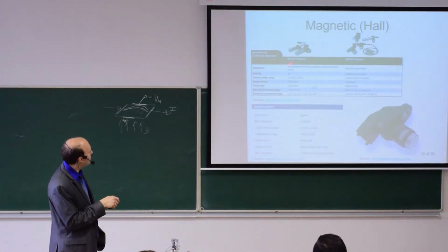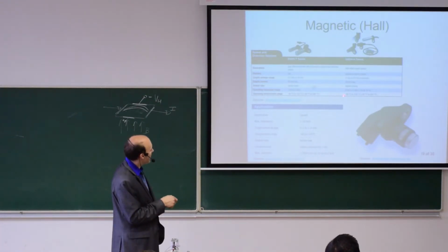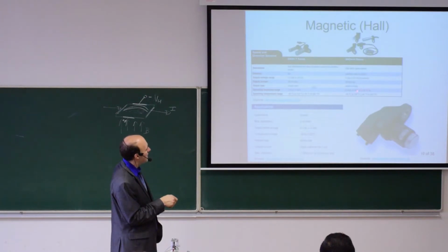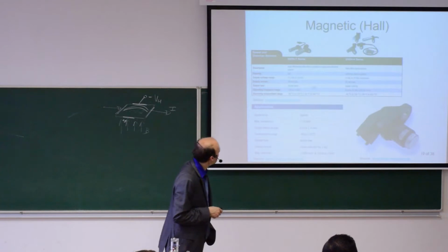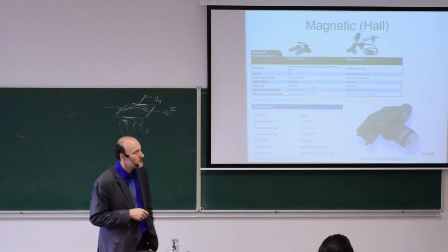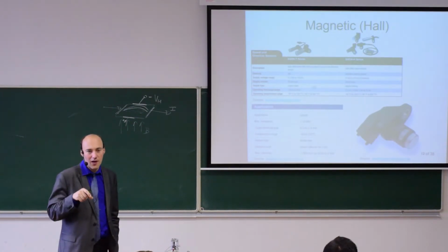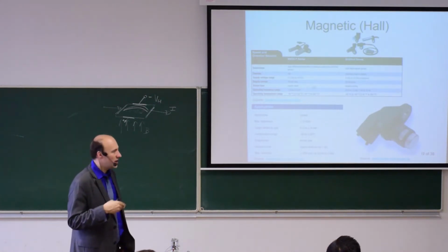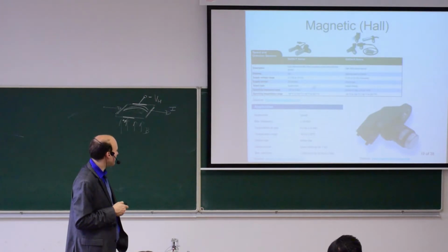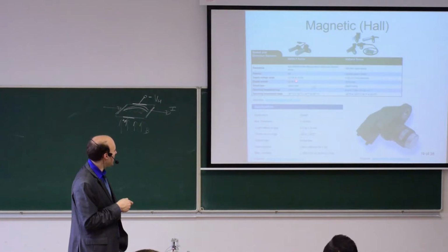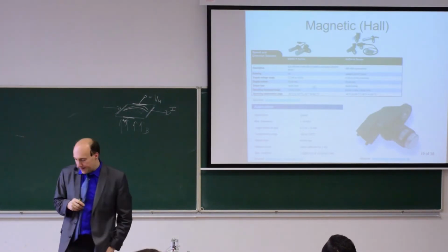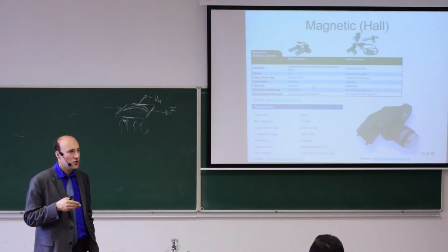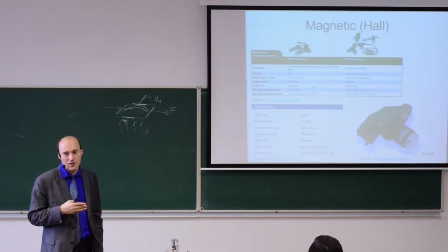What you see here again are two examples of automotive sensors. They say from 0 hertz to 15 kilohertz in one version. In another version there is a high pass filter, so from 2 hertz to 15 kilohertz, no, 15 hertz in this case. I think there is a K missing. And in this one you see they limit it above 1 hertz up to 15 kilohertz. So not all sensors based on this are able to work from 0 speed, but still 1 hertz frequency is quite low. You can see the power supply voltage range here from 4.5 volts to 18, which is well within the normal voltage that we have in industrial applications, which is 12 volts, sometimes 36 volts. In automotive applications, the normal voltage is 12 volts.